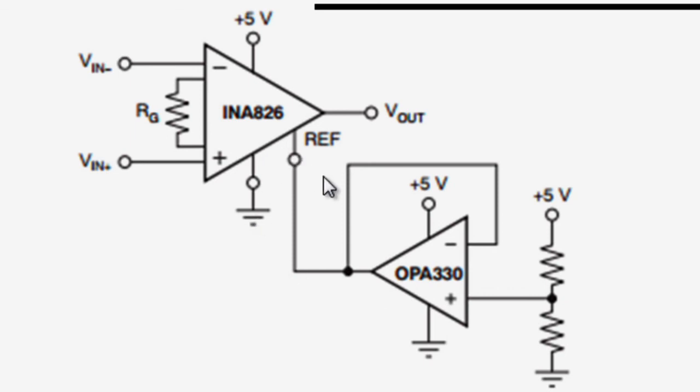Now this is important, an example for single supply operation where you're going directly into an ADC and you want to level shift the output. You can't just tie two resistors there. You need to make sure that you're either using a reference, such as the REF3225, or a buffered resistor divider. And that is what I have.